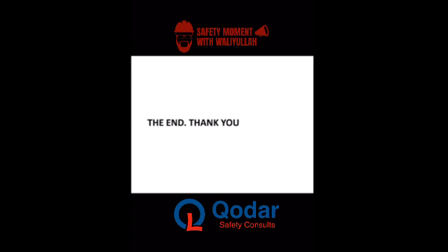What are those hazards that have to do with electricity, portable equipment, electrical inspection? What do you check out for? What do you look out for? Then he moved to working over overhead power cables, overhead power lines. It's still part of electrical construction. He explained this for us: the electrical zone, the hazard zones, exclusion zone, no tip zone, crossing point, assume it's live. These are the major points that have to do with electricity when it comes to overhead cable.